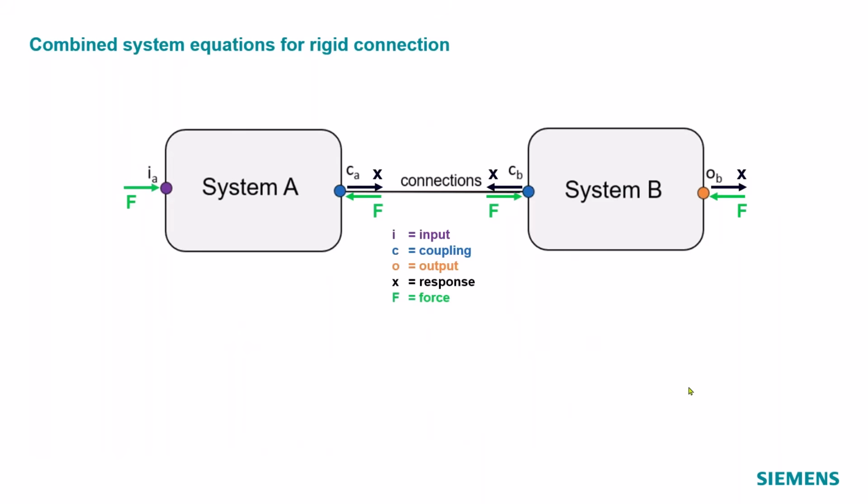Now, we're going to start working with this as a complete system. I'm going to make some assumptions here, again, for clarity. The principles I'm going to show are going to be for a rigid connection. Okay, so I'm bolting this subframe directly into my body. There's no elastomeric mount. From my past, the ride and handling guys would have loved this because it gives them ultimate control, right? As a noise person, I did not like this because it made it a lot louder. But for our discussion today, we're going to have it be a rigid connection.